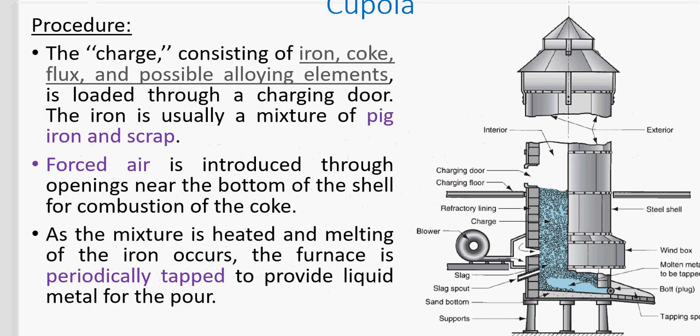So I'm just explaining the basic ingredients, their importance. And the first air is the hot gases used for the combustion. So after the melting, you have the iron beneath because it is denser, has higher density, and then the impurity, which we call slag, can be tapped a little bit above here. You can see the spout, the outlet for the impurity.